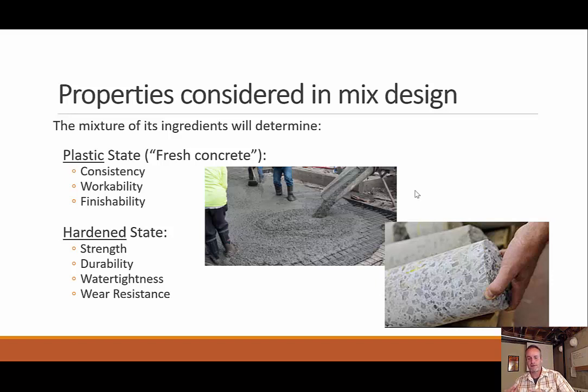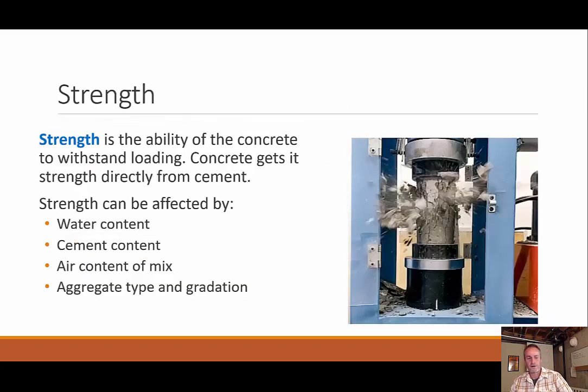What that basically means is how easy is it to spread around, get it into the voids, how easy is it to finish it with a trowel, make it look pretty afterwards, versus the hardened state after it's cured and hardened. Then we're more concerned with how strong is our concrete, how durable is it going to be, how much will it resist water penetrating into it, and will it be resistant to wear and tear.